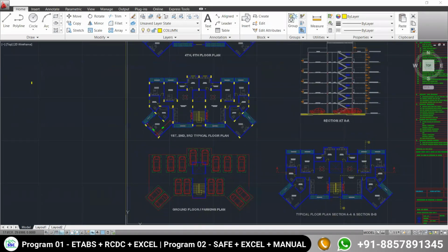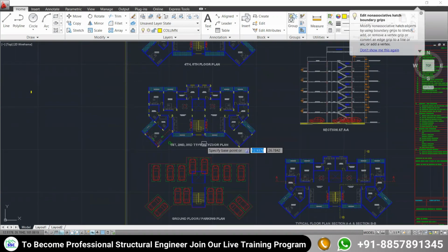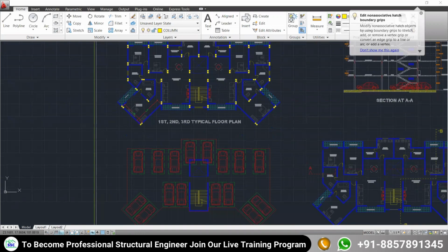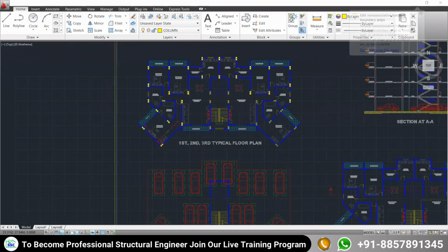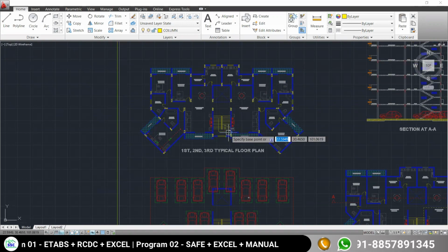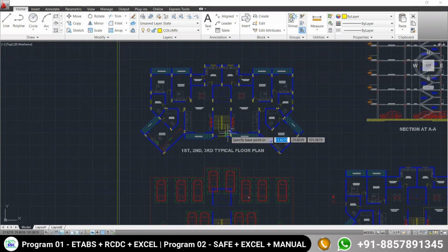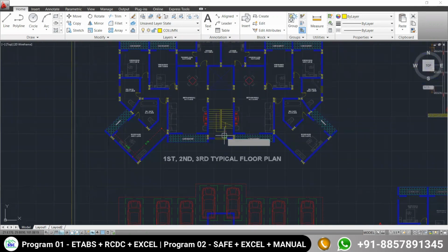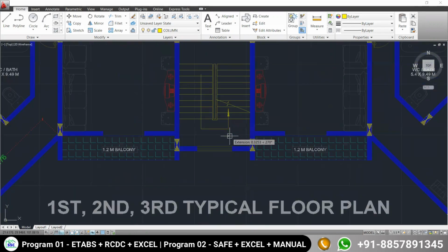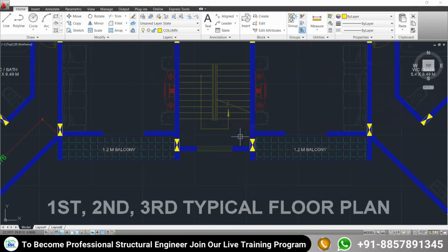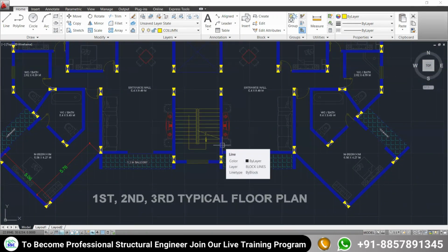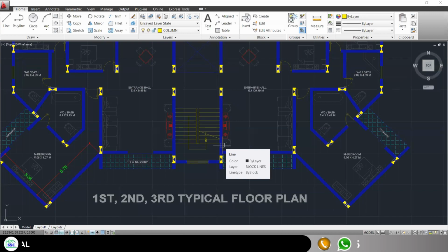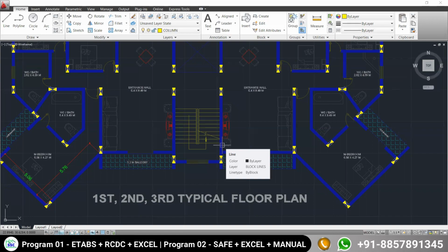So first of all, I'm going to take the column at the ground level. Is there any obstruction on the ground floor for the parking? So remember, every time you are going to check the positioning from one floor to another floor, take a common point that will not change throughout the height of your structure. आप लोगों को पता है, your staircase will continue from base to top. That is not going to change. Plus, if lift is there, the lift is also not going to change once it is positioned at one level.